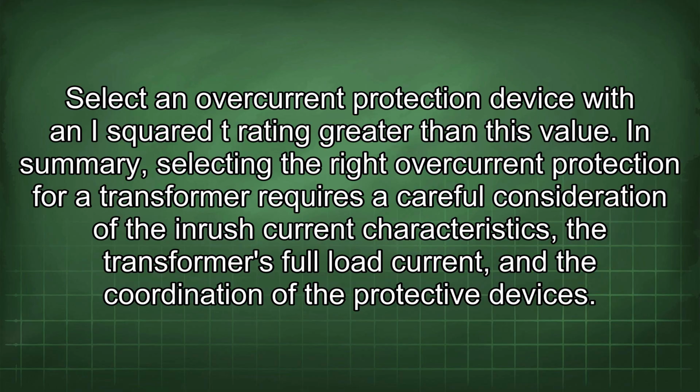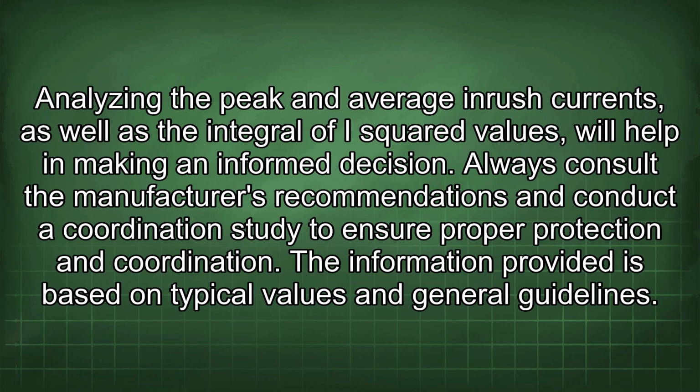In summary, selecting the right overcurrent protection for a transformer requires careful consideration of the inrush current characteristics, the transformer's full load current, and the coordination of the protective devices. Analyzing the peak and average inrush currents, as well as the integral of I² values, will help in making an informed decision. Always consult the manufacturer's recommendations and conduct a coordination study to ensure proper protection and coordination.